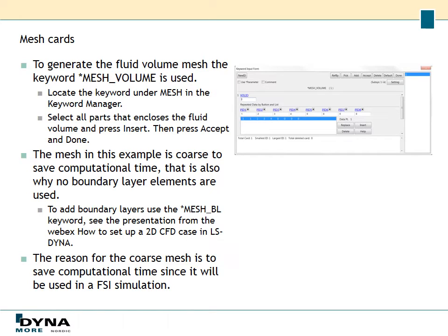And the mesh in this example is quite coarse, and that is to save computational time, and for the same reason the boundary layer elements have been removed.